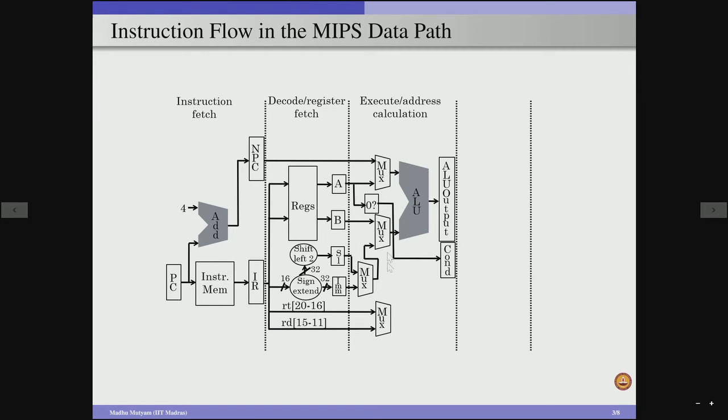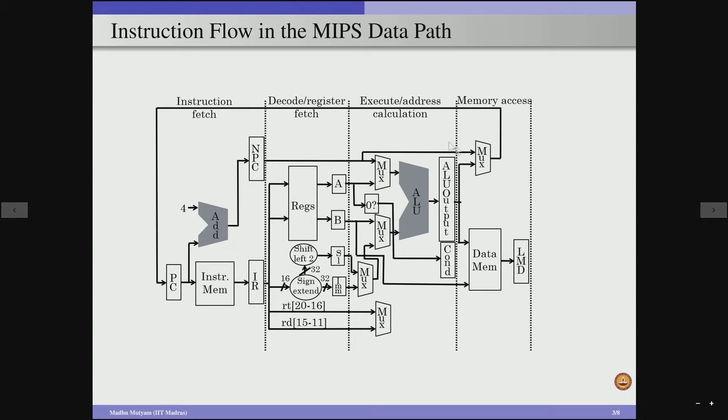and this ALU functional unit is the one which is actually performing the effective address calculation or the actual operation specified by our opcode, and the output will be stored in a temporary register associated with this functional unit, that is ALU output.